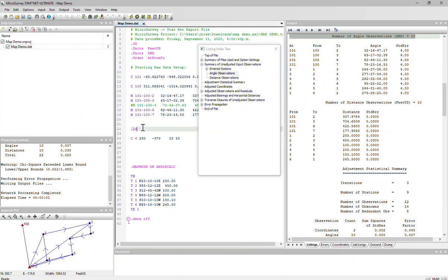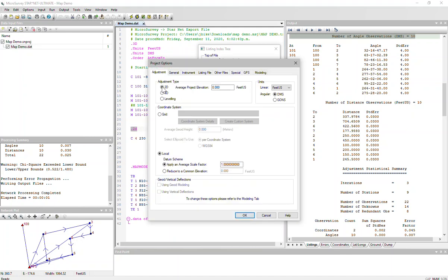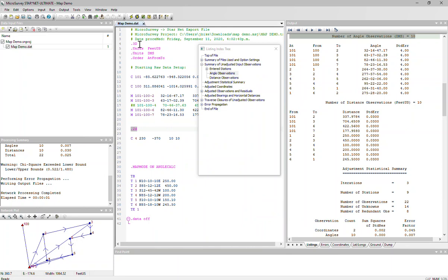And you'll notice how what I've done is I've used inlines in order to differentiate between 3D and 2D data. Because this old plan only has 2D data, you'll find in my project that I'm just running this as a 2D adjustment, but it was able to accommodate the 3D data when I used the .3D, and then I switched it over to 2D for my coordinate input, and then it stayed in 2D while I input the traverse information.